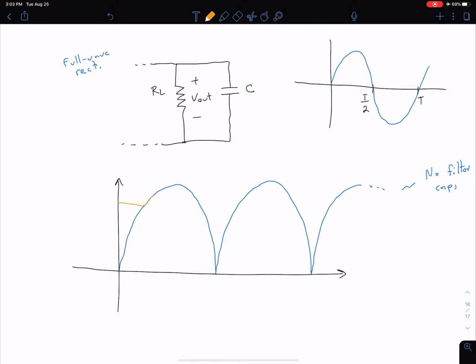So our capacitor is going to begin charging along with this curve. We then reach this peak value. So now our capacitor voltage is still larger. Our charging voltage has gone away. It's trending towards the other direction. So we're switching between, for instance, this positive half cycle towards our negative. And so what is happening then is our capacitor begins discharging through our resistor. That's going to continue until we get to this point here, at which point our capacitor begins charging again. And so that process, of course, is just going to repeat as we go through here.